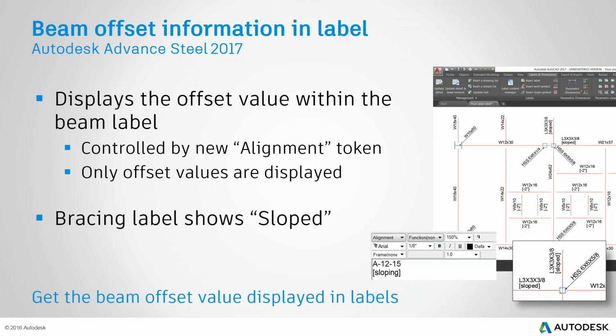You can see that some of them say they are offset to the view we're looking at directly. There might also be one that is not perpendicular to the view, where it tells us that the bracing is sloped. The offset value is in relation to where we're looking at the UCS plane, or whether it's sloping away from that plane.